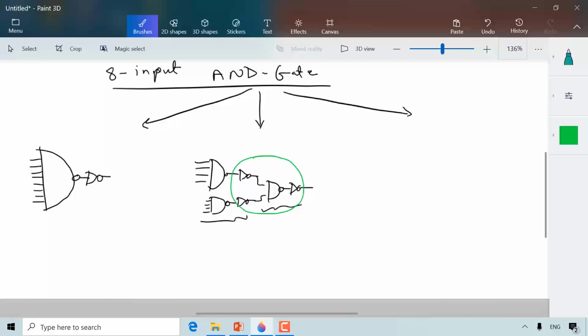by a 2 input NOR gate. So this is the 4 input NAND gate, the 4 input NAND gate, and then this one can be simplified by a 2 input NOR gate. Okay, so this is what bubble pushing and simplification means. So typically you use De Morgan's law to do the simplification.